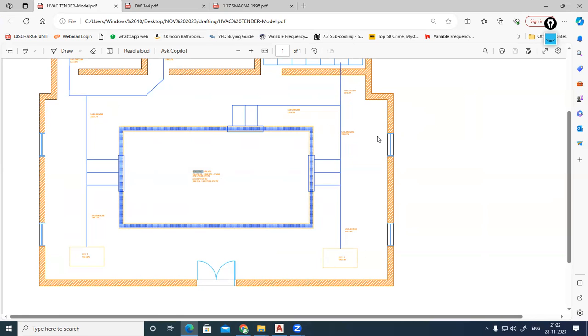The architect might be working parallelly in his system. Whenever the architect makes changes in the same architecture layout, other teams should get a notification, and only then can they change accordingly. If the room dimension, wall dimension or location of the wall is changed, we should make our own changes accordingly, right? That's why when you double click and open the architecture layout, it comes as a fresh architectural copy. Whenever the architect makes changes, you will not get the notification there.